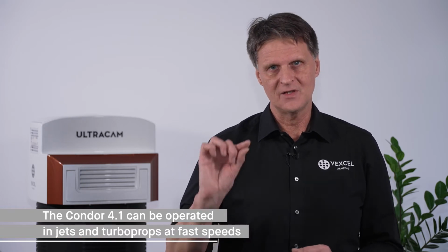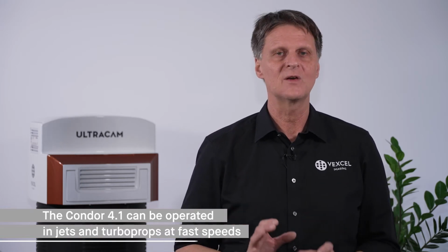To deal with all these smaller pixel pitches of the CMOS sensors, all lenses have been designed newly and they are all temperature controlled. We have temperature measurements across a lens so that we can later also do a lot of corrections and modeling for the utmost sharpness and contrast and geometric stability.